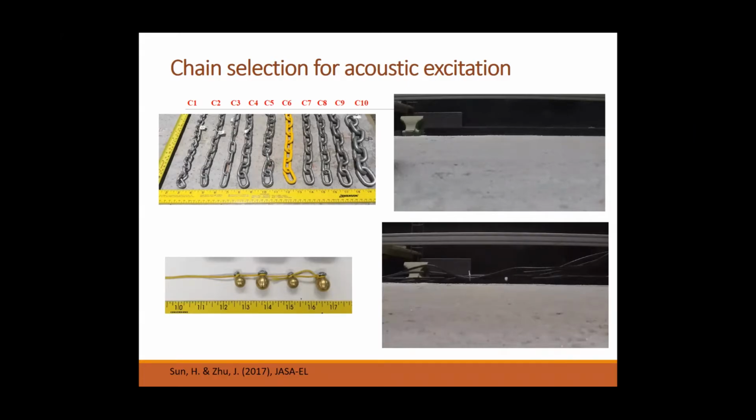But we know when we want to detect delamination, the hollow sound we hear is like when we play, let's say, a drum. When you play a drum, you tap or hit the drum membrane, but not scrape on the surface. That's why when we change the chain to the ball, because of the rough surface of concrete, it will jump and impact on the surface. So it gives a much clearer signal and much better improves the signal to noise quality.